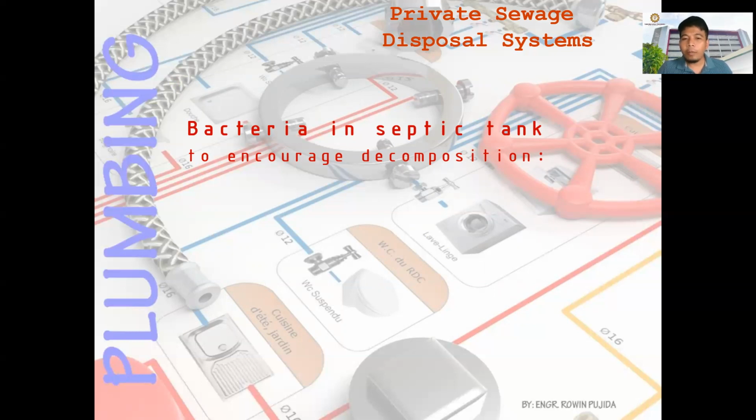In that case, your septic tank may be full in maybe 2 to 3 years, since the soap in your shower compartment or shower receptor can kill the bacteria in the septic tank, so the decomposition of the waste can be blocked, since the bacteria already died because of the soap in your shower drain that goes to the septic tank.